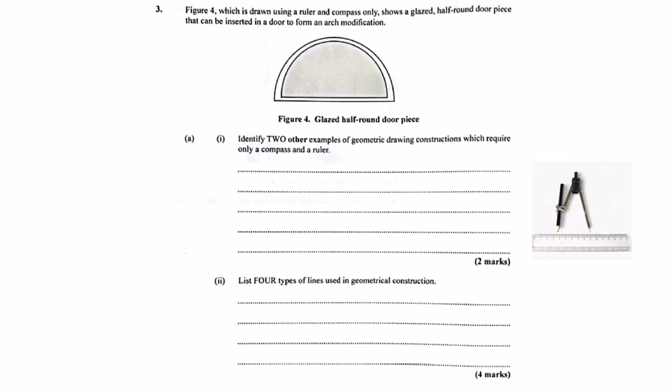Oh, absolutely. Think of these different lines as different types of information. Construction lines are super light, almost faint guidelines. They're temporary aids you use while you're drawing to get shapes and angles right. But they aren't actually part of the final object. Just guides. But you have object lines. These are thick, solid, bold lines. They define the main outline, the visible edges of whatever it is you're drawing. These really show you the shape of the thing. Okay. Light for guiding, bold for the actual shape.